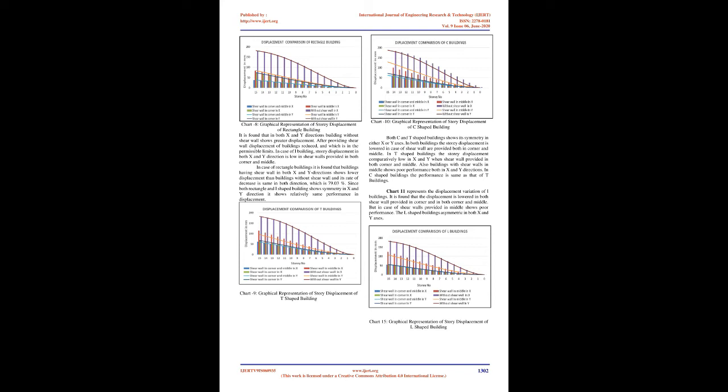But the load is not applied on base alone, as the lateral load is applied along the height of building, and building in turn has different stiffness and masses along its height in different storeys, so the reactive force in each storey due to lateral load varies, and this reactive force is storey shear. Roughly, storey shear can also be seen as distribution of base shear along its storeys based on its stiffness and mass. Chart 5, graphical representation of storey shear in X direction.